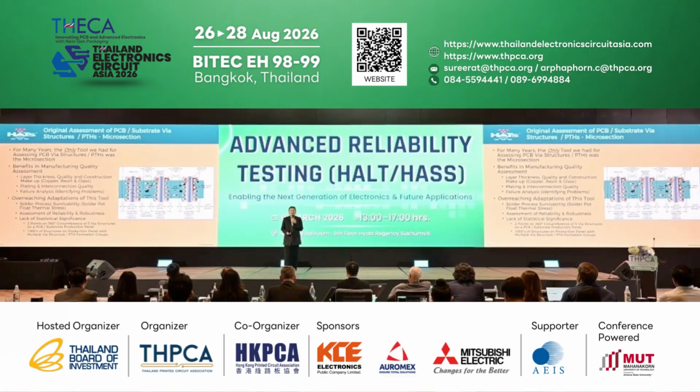Unless otherwise specified, by IPC standard, every coupon or PCB board before microsection needs to be treated by what we call the thermal stress test. So the PCB or the coupon needs to be treated first in accordance with thermal stress test to simulate what the PCB is going to experience in the assembly process.